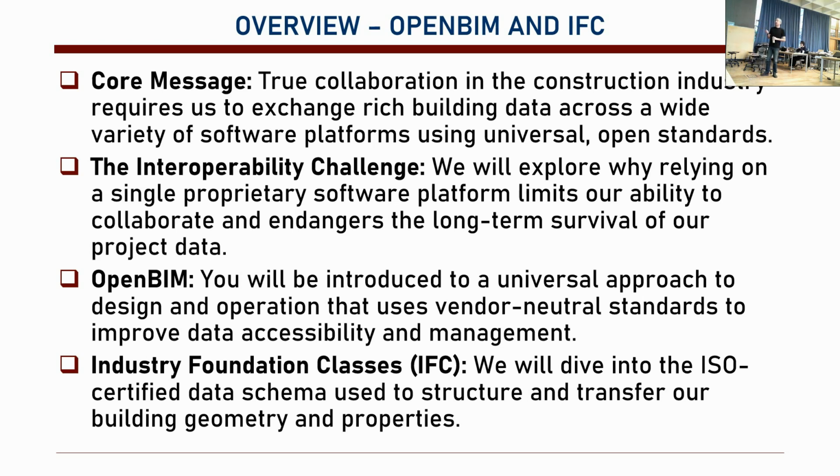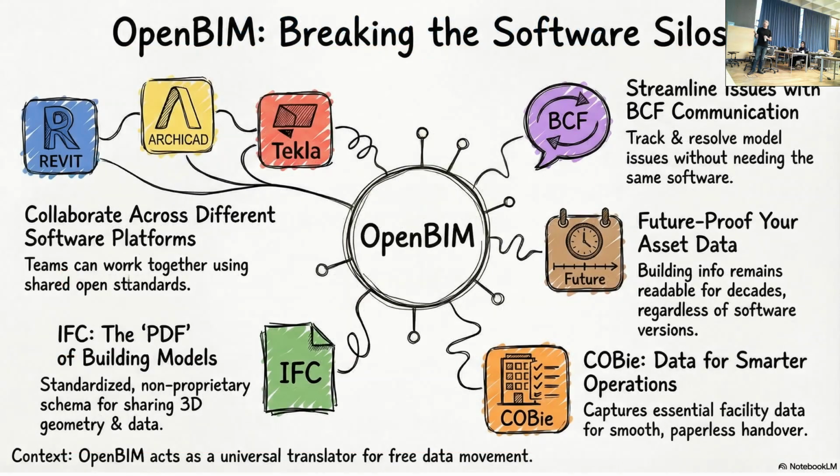Okay, first we will talk about why working on a single software wouldn't work in the construction sector, and why we need to have a way to provide long-term project collaboration, and how OpenBIM is proposed, which is using a new vendor-neutral standard. Okay, and then we'll talk about IFC. It's an ISO certified data schema, which is used to structure and transfer building geometry and properties. So we'll talk about that.